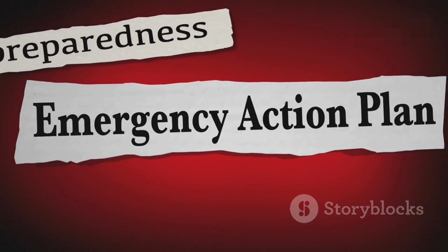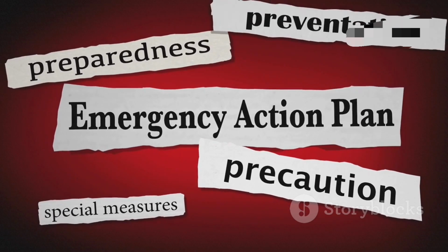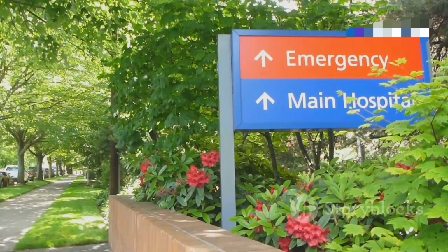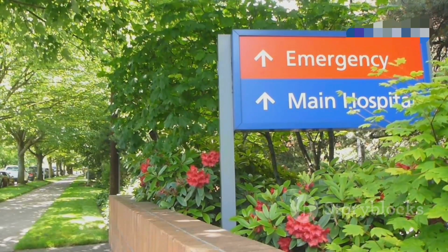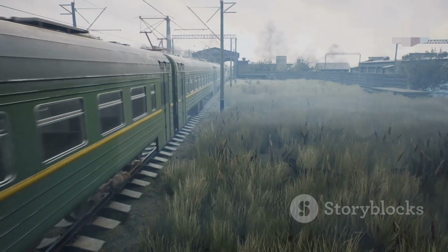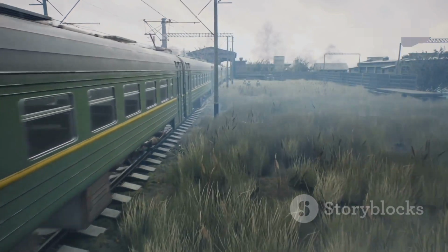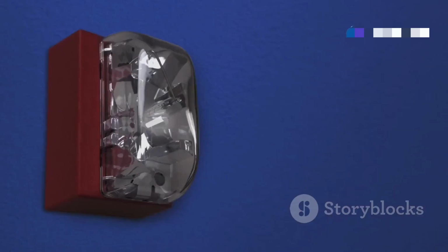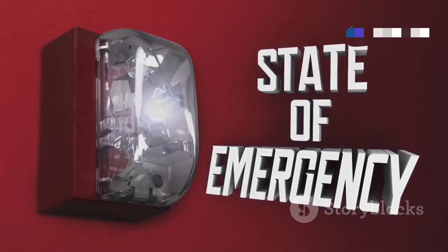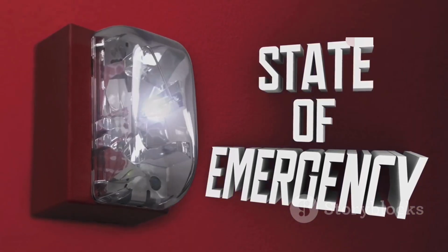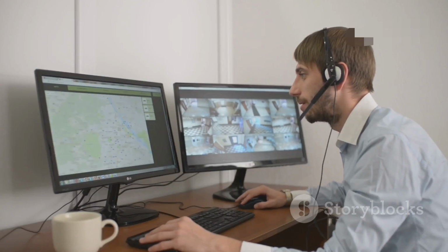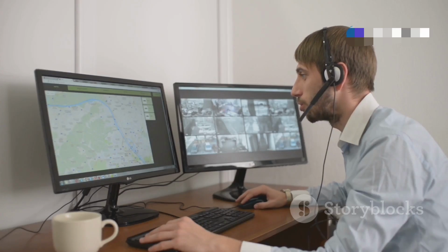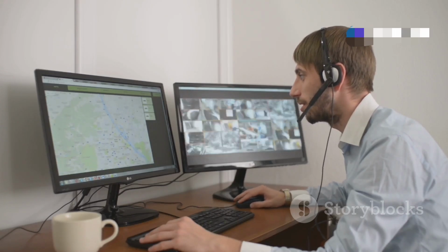The outputs from HEC-RAS dam break models driven by these breach parameters are fundamental to developing effective emergency action plans, or EAPs. EAPs outline procedures for warning, evacuation, and emergency response. The predicted flood arrival times, water depths, and inundation areas inform evacuation routes, shelter locations, and the timing of warnings. If the breach development time is underestimated, the available warning time in the EAP might be insufficient. Therefore, the integrity of the EAP and its ability to save lives and protect property hinges significantly on the quality of the underlying dam break modeling and parameter selection.